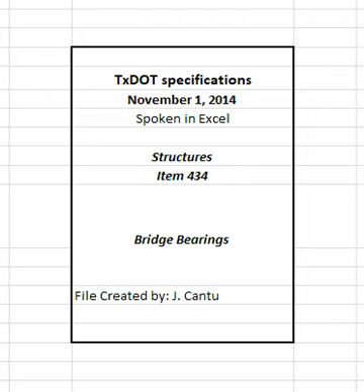3.3.2 Testing and Acceptance. Coordinate arrangements for sampling and testing with the construction division before manufacturing all or a significant number of bearings for the project. Coordinate with the construction division the number and type of tests that must be observed by a designated construction division representative. Perform testing in accordance with Section 18, Bearing Devices, of the current TxDOT LRFD bridge construction specifications. Use pre-qualification for certain tests only if approved by the construction division.